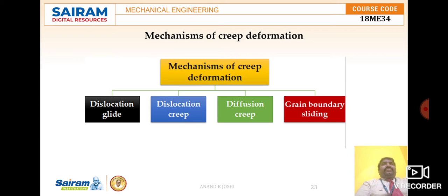We already know that plastic deformation occurs due to the movement of dislocations in a material. However, the movement of dislocations can be stopped by obstacles such as grain boundaries or the stress field around solute, that is impurity atoms, and even by the strain fields of other dislocations. Dislocation pile-up starts to occur at obstacles.